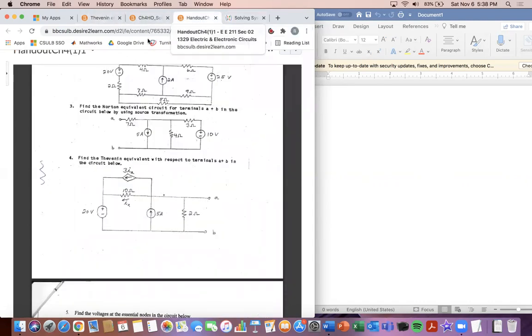So what I think of as V Thevenin is the node right before, see how the open circuit occurs here. It's this node right here, the one right before that occurs. And the reason being is then this resistor would be in series, and so that would work out. And then we'd have our open right here. So what we need to do is form, I'm going to say node voltage would be the easiest here. Just for me, I find it easier than doing mesh currents.